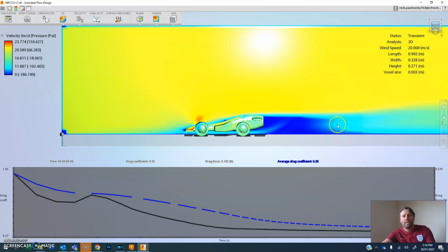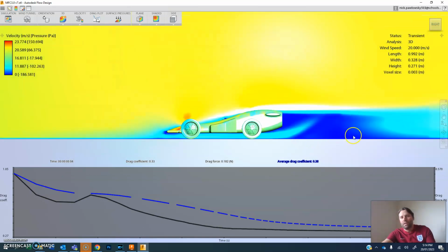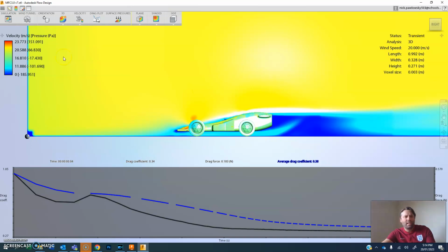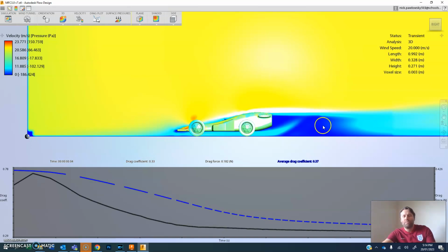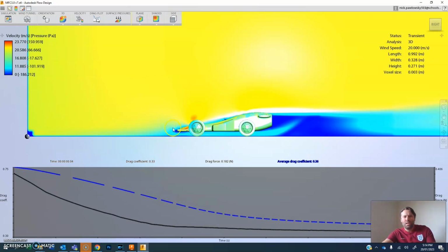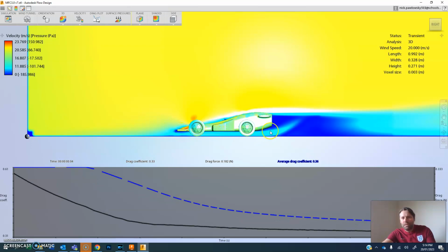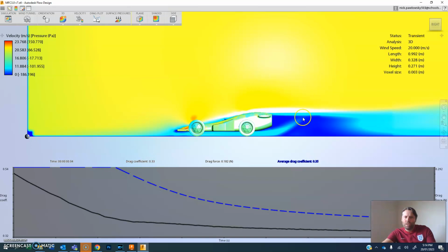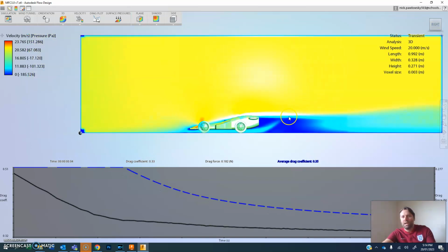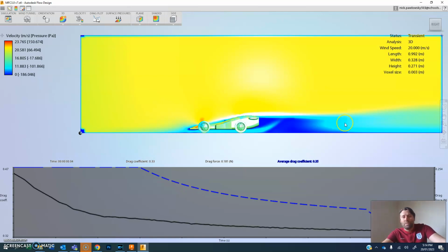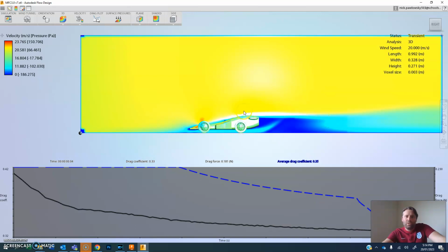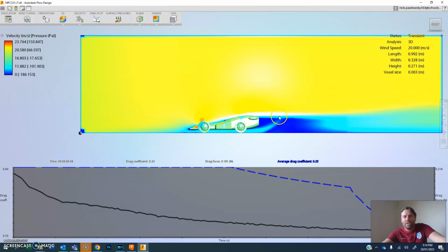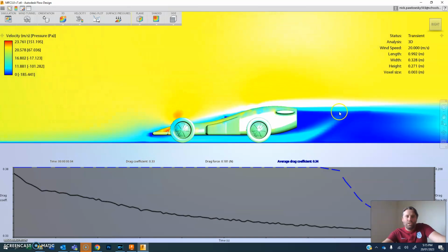Generally, what I would look at is this flow behind the car. This blue space, as I said, is sort of sucking back on the car. All this dark blue stuff is negative pressure and it's pulling the car backwards. So what you want is to allow a little bit of air to come underneath, just like you can see on mine, and you're trying to make this blue wake behind your car as little as possible. You want it to feather out like a triangle behind your car, rather than being a big block.